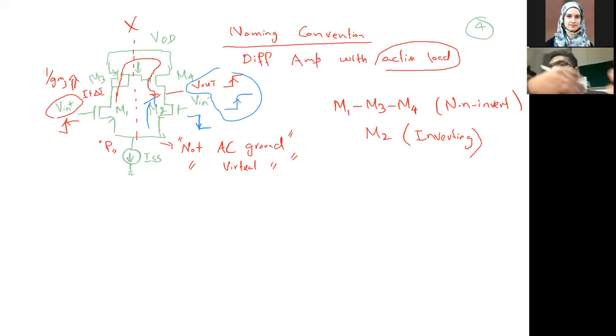Ultimately, as I showed at the start, we can also have a PMOS structure and an NMOS current mirror. In an NMOS current mirror, the scenario is going to be opposite. This M1, M3, and M4 are not going to behave in a non-inverting way, rather it will also behave in an inverting architecture. So you need to see which behavior and how you are going to analyze the circuit. So for that, you need to make sure the two loops concept, that how they are enhancing the V out, ultimately is clear to all of you. So make sure to clarify this point.